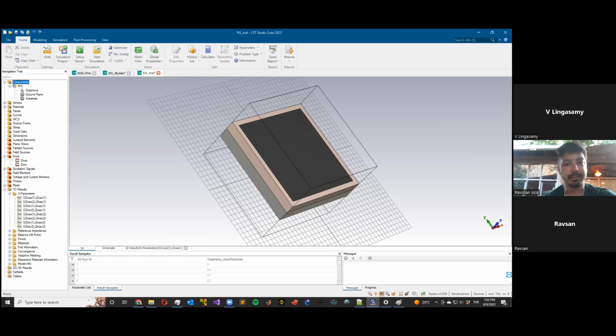But you agree, right, that we check the S11 parameters and the phase response, and CST Studio here is a good enough tool to measure and to understand. Based on one cell, we can then model and construct the array.